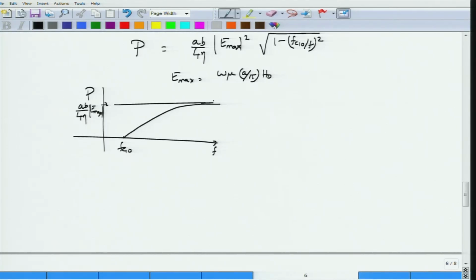Okay. This would not be completely correct because this only assumes that the TE10 mode is the one which would be propagating throughout the frequency, but we do know that after some time TE20 and TE01 start propagating, then you have TE11, TM11. So all these things would actually drop the power. In other words, they would also start carrying some amount of power, and if your operating frequency happens to be say here, then you actually have power distributed in 3 different modes. So some power carried by the fundamental, next power carried by the next higher order mode, and the other higher order mode. So all these would share power depending on how much power you have put in and what are the corresponding factors for fc10 and f that you have to calculate.